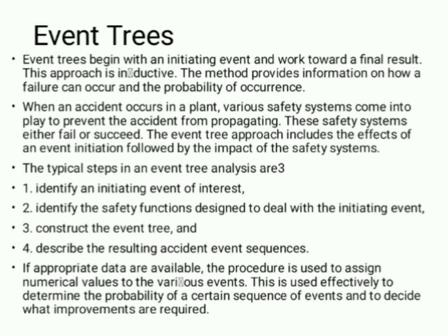If the coolant is not provided properly, the reaction temperature will increase, and the increase in temperature will increase the pressure, so there is a chance that an explosion will take place in the reactor. These are the sequential events that may cause a failure or an accident. Generally, this is called a runaway reaction.